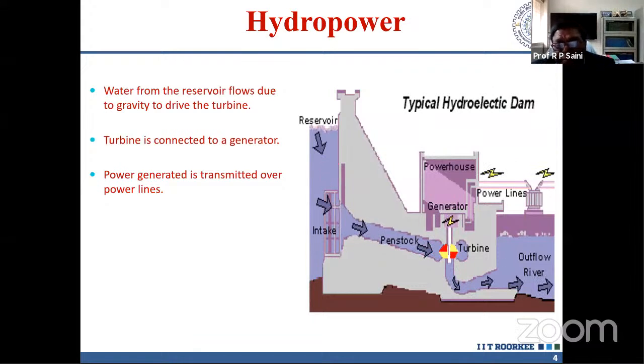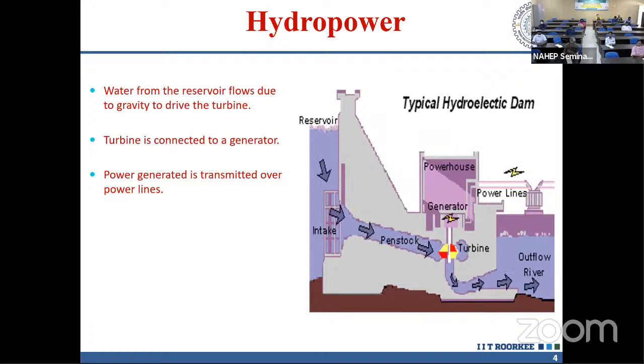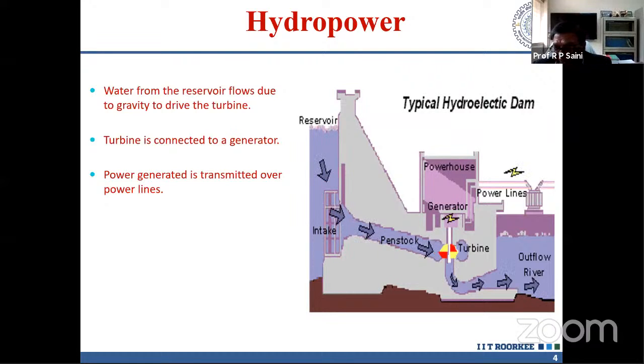So this is the thing that we have to understand. In order to estimate the potential of any renewable energy, I'm talking of hydro, you have to use some power equation. Power equation means, because the energy or the potential should be in some quantity, and quantity will have some dimensions. In that case, this mgh is the potential. What is h? h is the vertical height. It's not the length of any water conducting system.